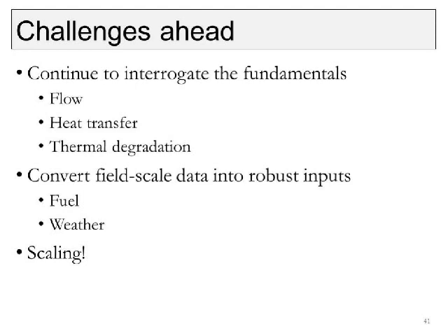Aha, here's a question. Tim asks, did you use any turbulence modeling in the system? Yeah, so the code is large eddy simulation, so we have a subgrid scale turbulence model built into it. It uses sort of an algebraic approach, so we're not solving a conservation equation for our subgrid scale turbulent energy or anything like that, but we are accounting for the turbulence.